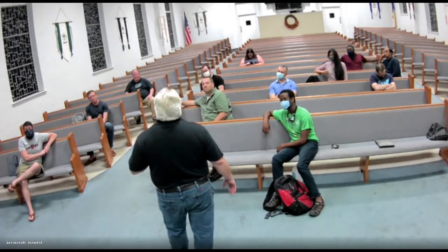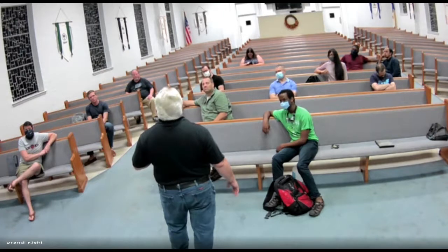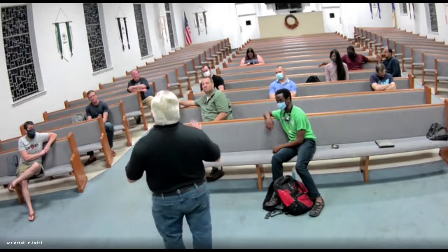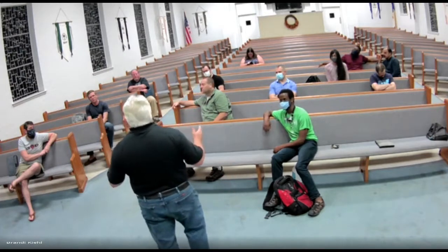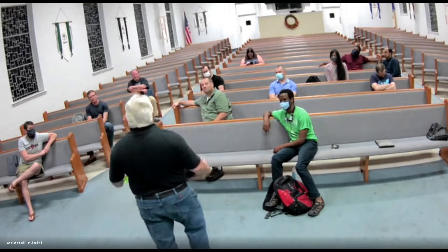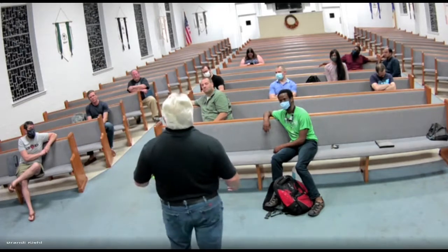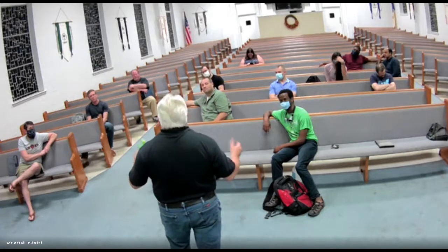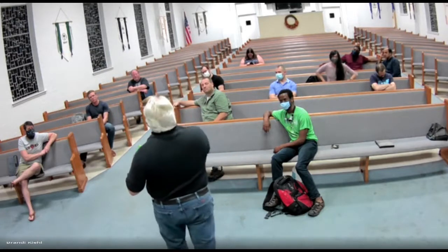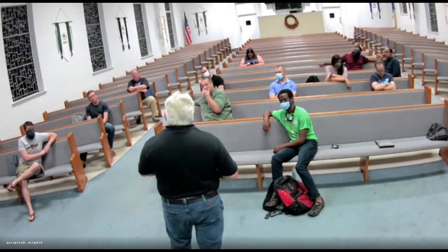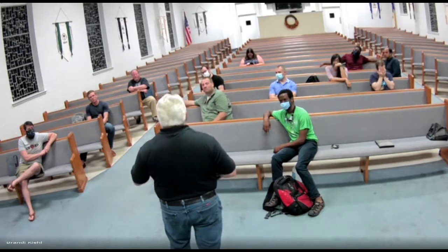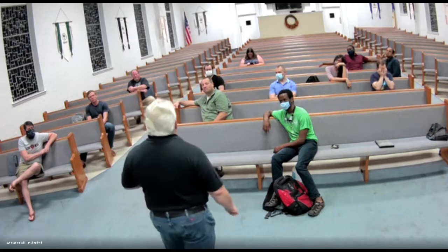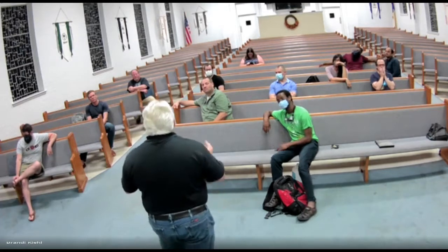The Honda EU series, the inverter generators, not so much. They're slap full of computer stuff. But if you have them, and you're going to laugh, put them back in their original box that they were shipped in, just because it's a nice sturdy box. Go into the kitchen when the wife's not watching and steal the big roll of aluminum foil and put aluminum foil around it this way and that way, and tape it up good, and put a second layer on there. That will be damn near impervious. It's probably 40 or 50 dB of pulse reduction just from a couple layers of aluminum foil, as long as there are no cracks.